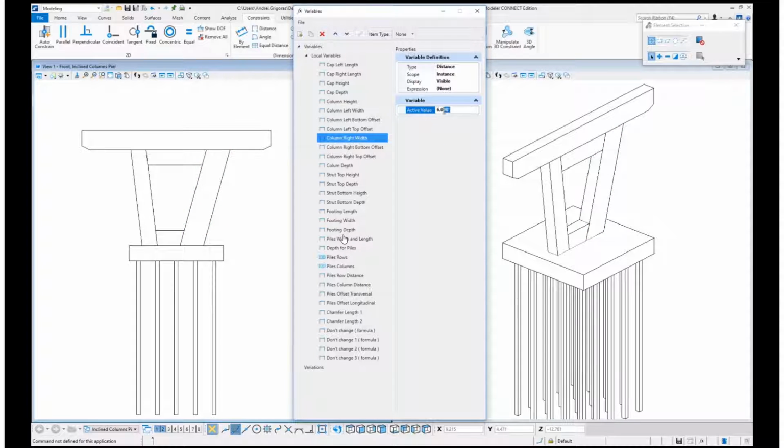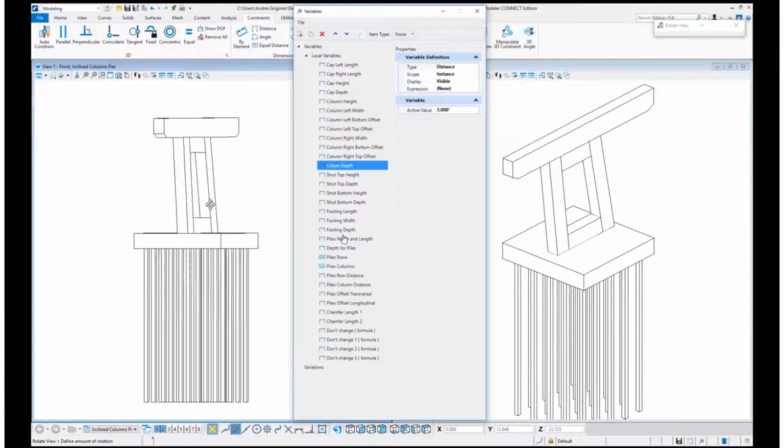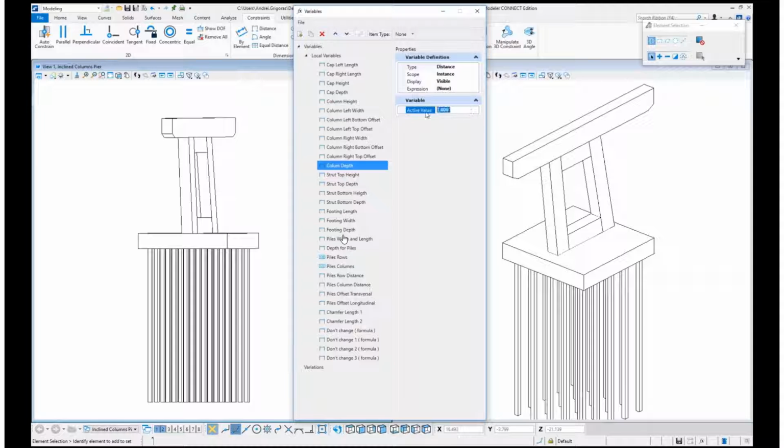So it's just a modeling tool for you. All these parametrics were included into this particular pier to achieve all the case scenarios. And it doesn't warn you that, oh, this column is almost going away from the footing. So you just have to double check your work on that. There is no error trapping achieved on that model itself. See?